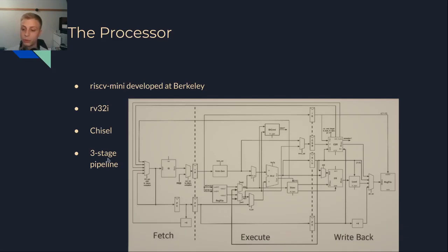The reason why I went with this was that I worked on implementing it in a hearing aid, where frequency isn't the most important part, but size and power consumption is. So when you have very high power constraints, you will often use lower frequencies to actually conserve the power. Therefore, it's better to perform more in parallel than it is to have higher frequency in your circuits.